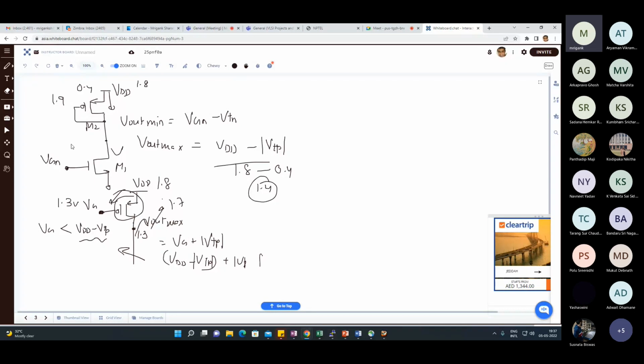Same is true when you look at differential amplifier with this kind of load. A differential amplifier can also have this kind of diode connected load, and also this kind of current source load. From the point of view of gain, I told you what the benefit is. From the point of view of bandwidth, output impedance here is low, therefore the pole at the output node is high. But in terms of swing, you are definitely getting a disadvantage, because the moment you use diode connected load, upper side swing will be limited. Is that clear, all of you? Any problem?